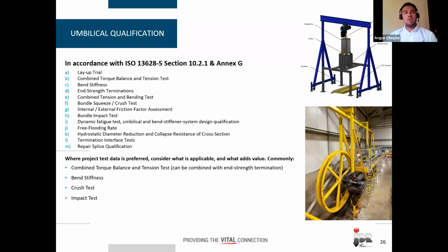Otherwise, if you want to have certain project test data, you should consider what is applicable and what adds value. So commonly that would be the tests listed here, which, if you have any background in this area, you'll see are the sort of tests that would drive inputs for tensioners and rock dumping and installation spread parameters. So it means that you can get accurate data to the installation contractor rather than using design calculated methods.